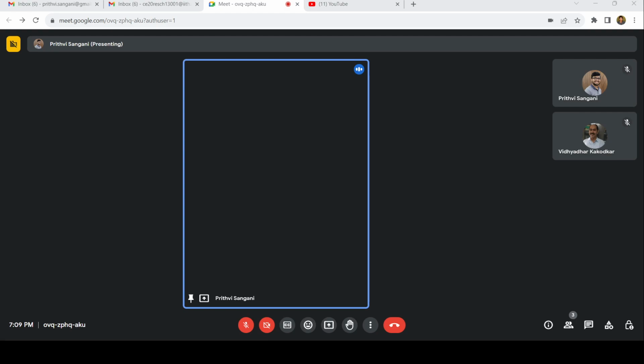So for that, F1 is 52.3. This is in tension. So that is 52.3, and U is going to be 1. Li is 8 meters divided by AE, plus even in BC we have 32.3 as our tensile load, and okay, this is compression.